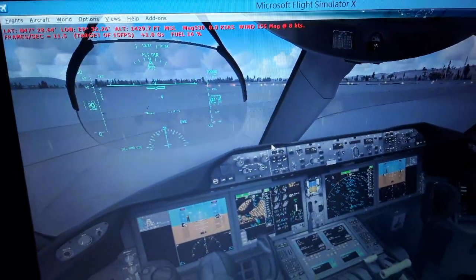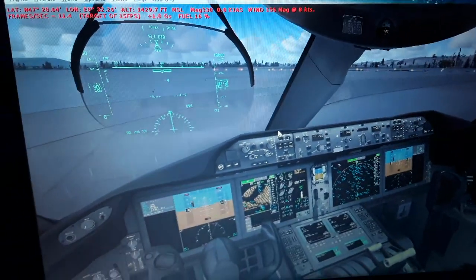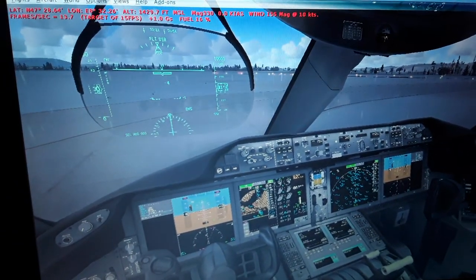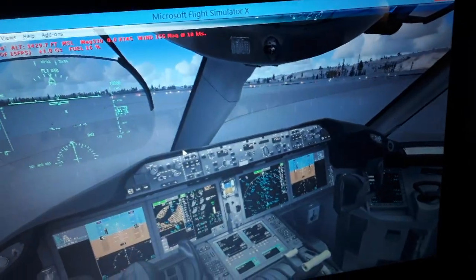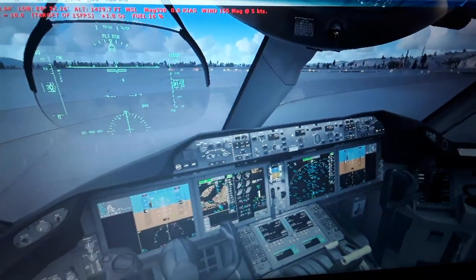Also, we have the navigation display that displays the horizontal and vertical profile of the aircraft as it flies. You can see terrain and weather reflections from the weather radar displayed in red, green and amber or yellow color, and also the lakes, rivers and sea in blue. We can see also the four-letter name of each airport. So we have our own airport displayed in the navigation display with a four-letter name.